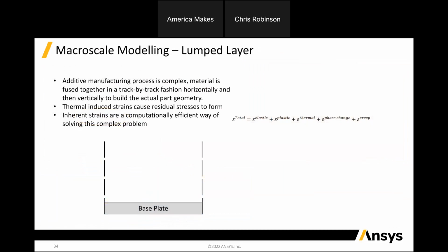I'm going to move fairly quickly here. In almost all additive process simulation, you're going to be looking at some level of macroscale because it's very efficient. The idea here is that you take multiple powder layers, your physical layers, and put them into a certain element size. When you're running the process simulation, you're going to consolidate a lot of that information into an element thickness, which is usually larger than the actual powder layer thickness. And so this is that next level up analysis. With Ansys, you can do that mesoscale and apply it to the macroscale.